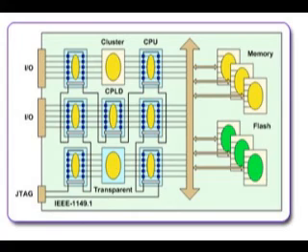Boundary scan tutorial. Since its introduction as an industry standard in 1990, boundary scan, also known as JTAG, has enjoyed growing popularity for board-level manufacturing test applications. Boundary scan has rapidly become the technology of choice for building reliable high-technology electronic products with a high degree of testability. Due to the low cost and IC-level access capabilities of boundary scan, its use has expanded beyond traditional board test applications into product design and service.